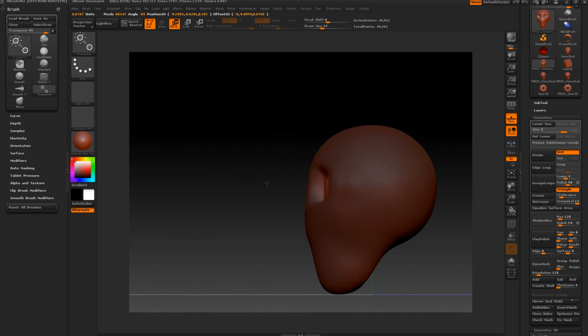So you have 3 options of modifying the geometry using the move tool. Same with scale and same with rotate. If you click on the empty white area and release your transpose tool on the empty area, you can then rotate around this pivot point by just clicking on the red circle on this side and rotate like so, and rotate around this pivot by just clicking here and rotating around. But we just need to move it inside like so.